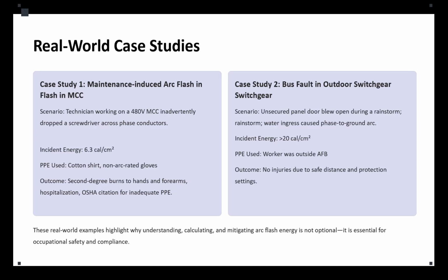This condition violates key NFPA 70E guidelines, which state that energized work requires a justified energized work permit. The maintenance worker should be certified. There should be arc-rated clothing suitable for that specific incident energy level, and we should have proper insulated tools and barriers. So we see that we missed several aspects of the guideline.